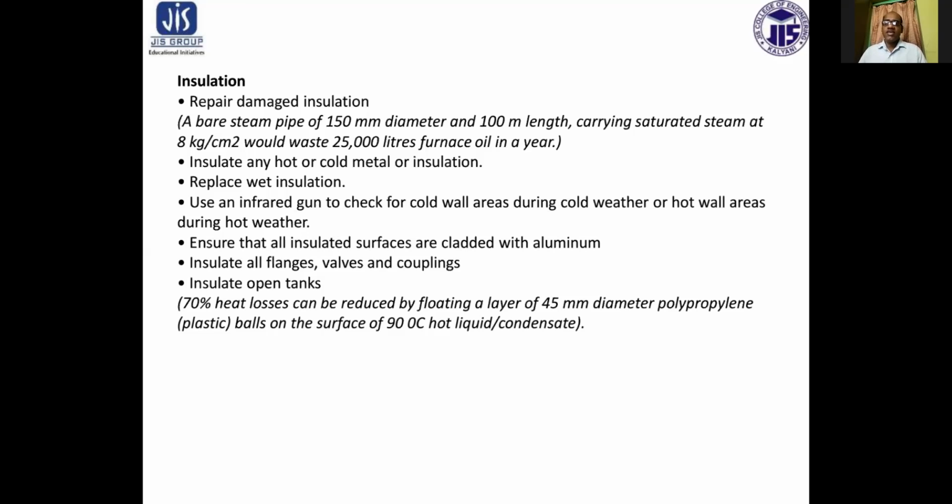Insulate all flanges, valves and couplings. Insulate open tanks. It is found that 70% heat loss can be reduced by floating a layer of 45 millimeter diameter polypropylene plastic balls on the surface of 90 degrees centigrade hot liquid condensate.